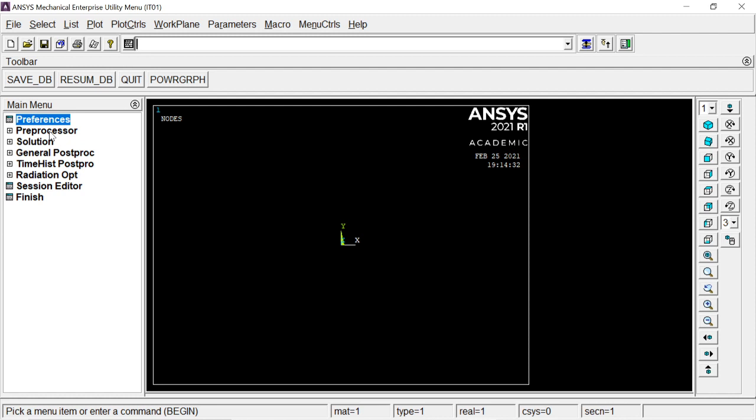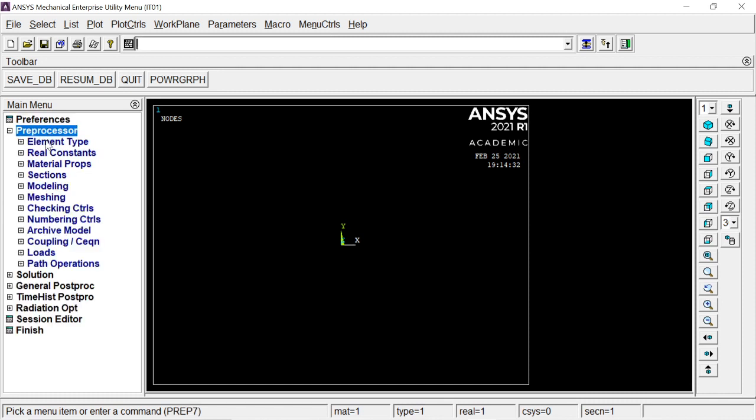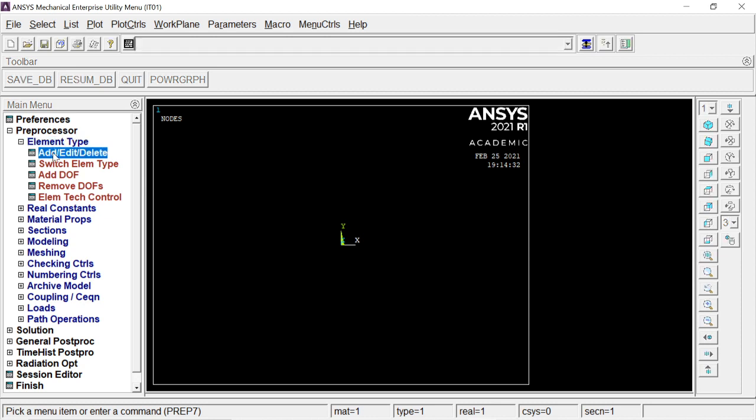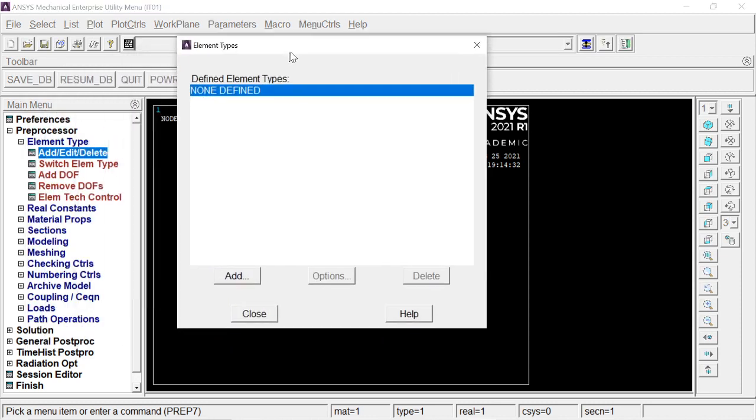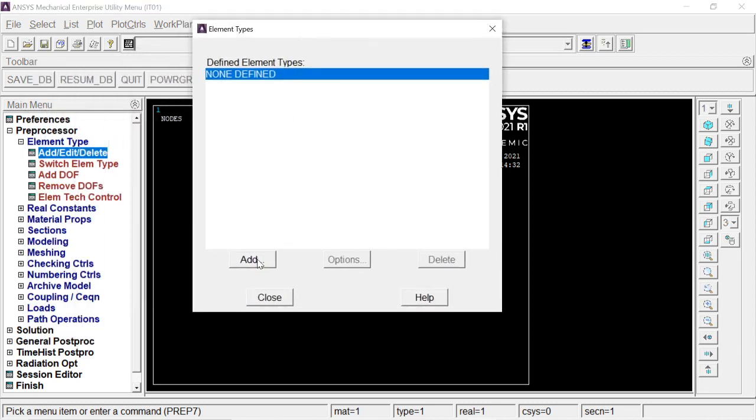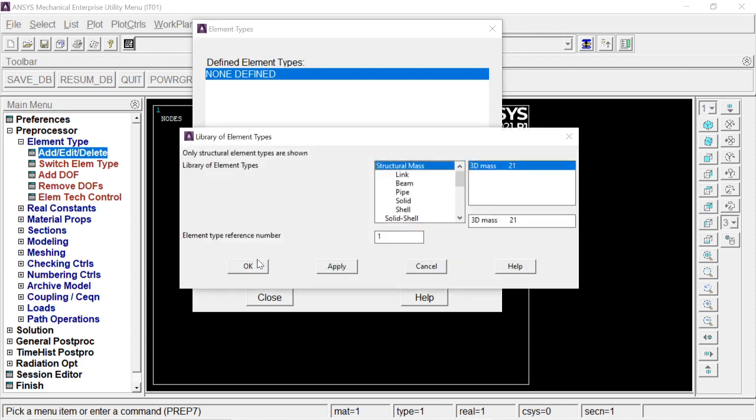So second step is pre-processing. Now most of the part of your Ansys, creating a problem and giving inputs, all things will be given in the pre-processor. So we are going into pre-processor now, starting with element type. Now which element to add? We will be solving this problem using 1D analysis, basic analysis. So you can select the link element and select the link 180.